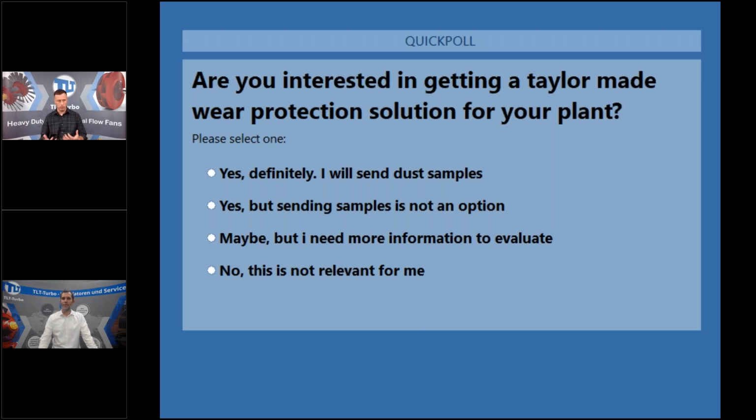And while you are polling, we'll talk a little bit more about some of the solutions. Some of this doesn't happen overnight. We might even work with a customer and end user over maybe 2 life cycles of a set of blades. You can look at the primary information. Usually fan blades are installed during that time period, so you let that cycle run out, and then you either try sample blades or you move on to the coating that we feel is the best solution for your system. And that's what's actually going to determine your increase in life and the longevity of the fan system itself.